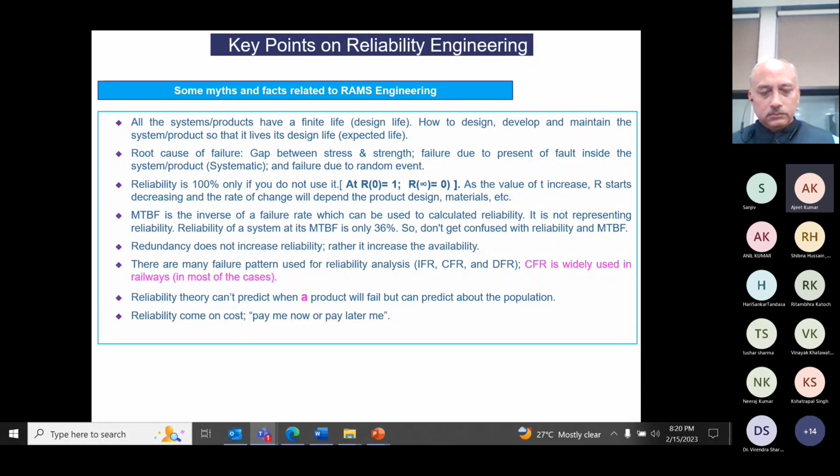Maybe the brake comes from some other company and the gearbox from another, and they are put into the assembly. Every component level has a specified failure rate and MTBF, and the subsystem level MTBF is specified so that overall availability will be increased.